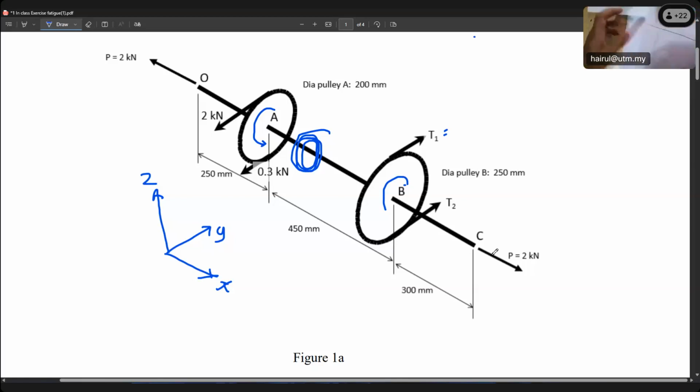So bending versus time is not going only positive; it is completely reversed. When it goes to tension, it has a value of tension stress. When it goes to the bottom, compression stress, same value. Bending versus time is like this. So their mean is 0, but they have sigma A. The sigma bending we calculated from the beginning times Kf bending is only alternate. So they have sigma A.